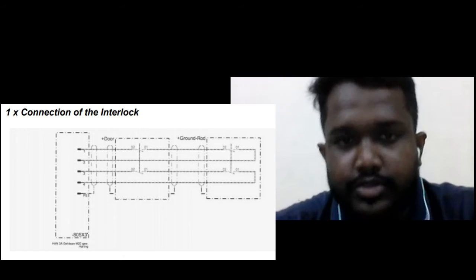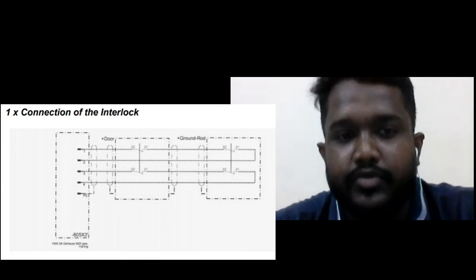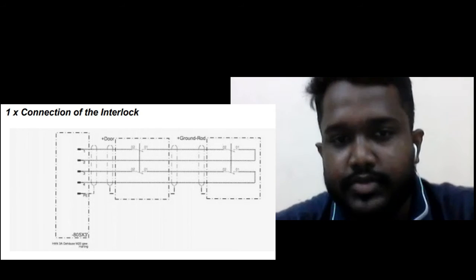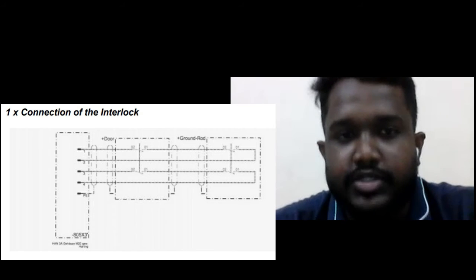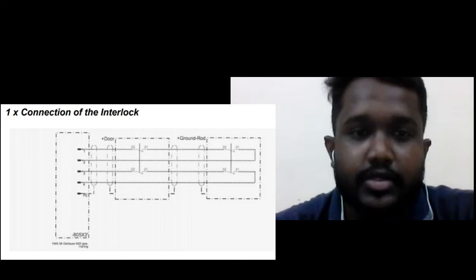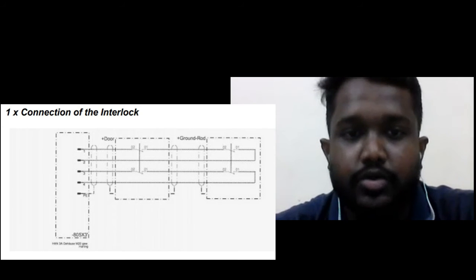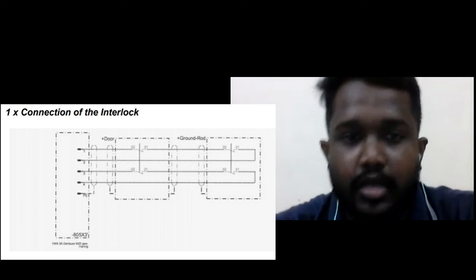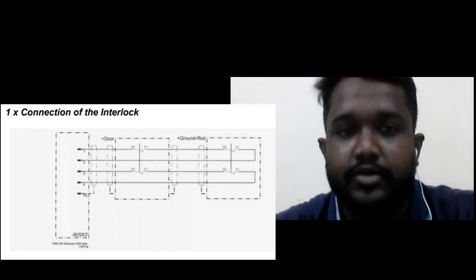You can also use the delivered Harting plug with 6 pins to connect the interlock. Take care that the two normally closed contacts are used together. The interlock works with dual channel operation, so it monitors the discrepancy time between the two contacts, and it has cross short detection to prevent connecting the two circuits together in a fault case.